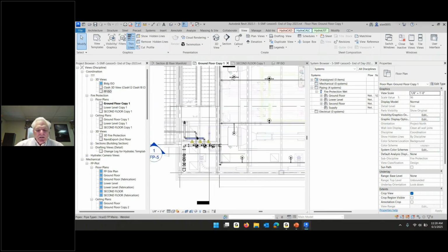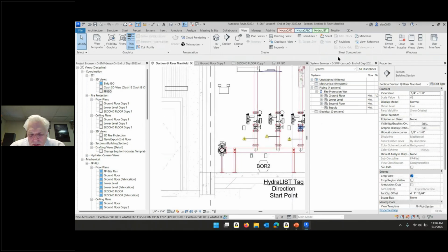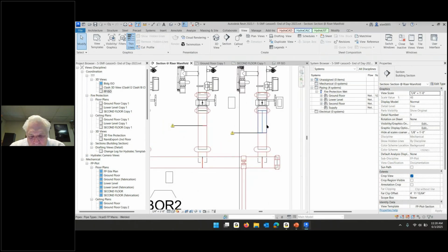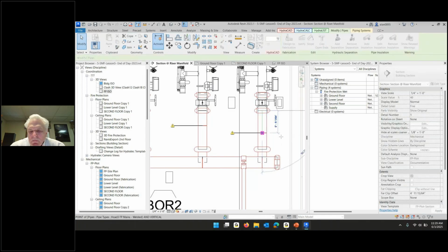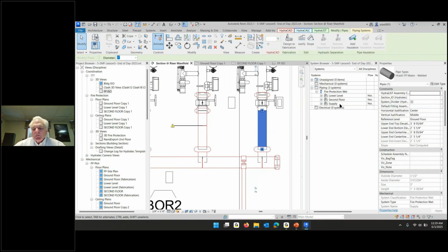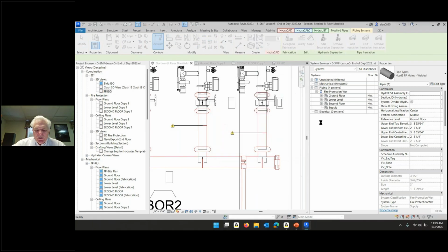Okay, so I still have these 3 darts that says the riser's not connected into. And I'm gonna show you the problem here. I have 4 systems, and I'm gonna take this pipe and reconnect it to that pipe. And now I've only got 3 systems. It said, oh, that's connected. I'll put it back together. So if you physically separate it, you get your performance back. As soon as you put it back together, the performance goes to hell again. I'm going to do undo to get 4 systems back.